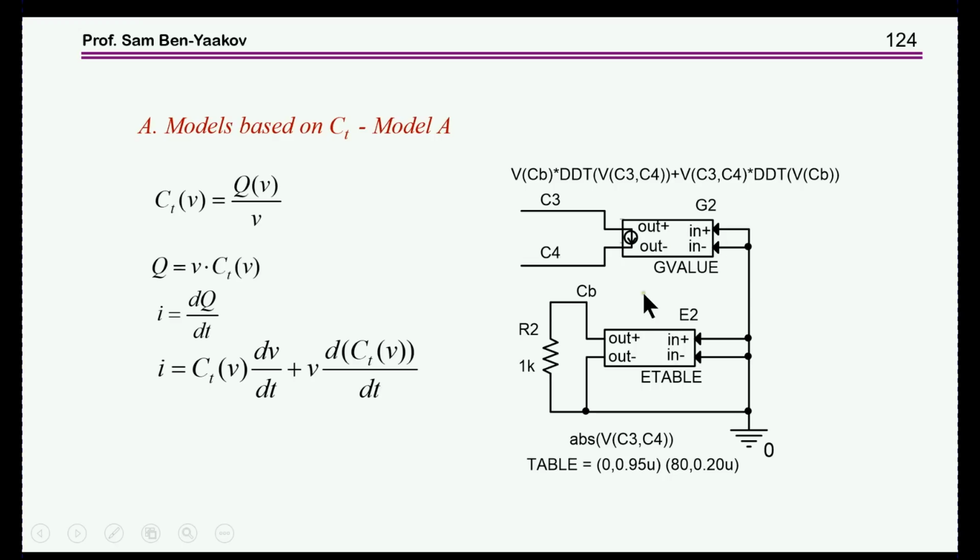It depends on an expression that you write. This is the current source, and I'm labeling this C3 and C4. This is the capacitor that I'm emulating. These 2 points are the capacitor, and they go into this current source. Now the current source has to follow this equation.